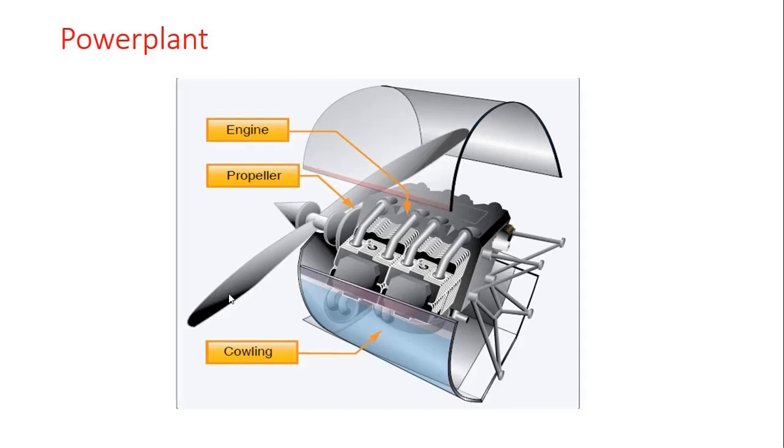The amount of lift being produced by the propeller is directly related to the angle of attack, which is the angle at which the relative wind meets the blade. The angle of attack continuously changes during the flight depending upon the direction of the aircraft. The pitch is defined as the distance a propeller would travel in one revolution if it were turning in a solid.